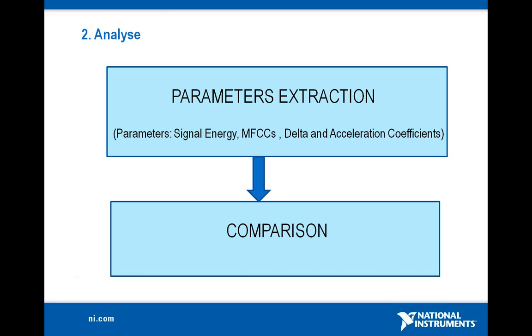To improve the reliability of the recognition system, 4 to 6 sets of such voice commands are stored in a database as a reference. To compare the sequences, we use dynamic time warping for time and speed varying sequences, or the Needleman-Wunsch algorithm, Smith-Waterman algorithm, etc. to figure out what was the word or what was the command that was given in the voice.